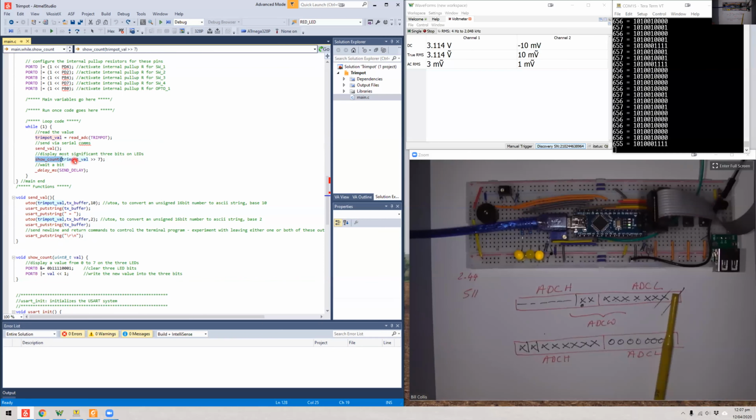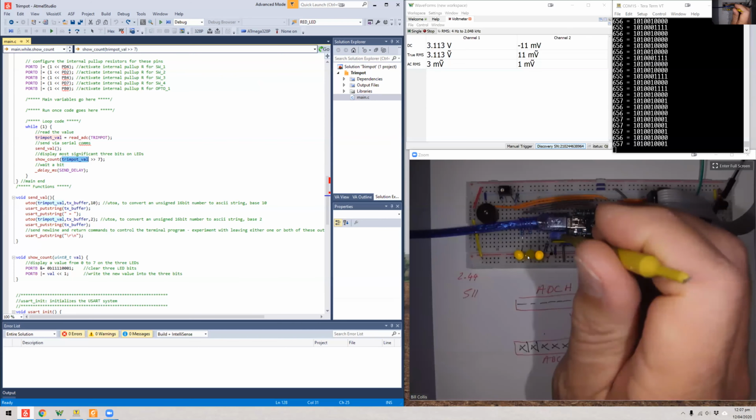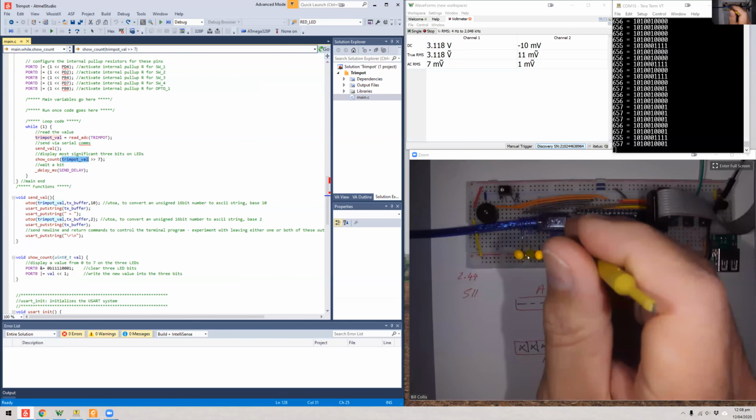And what I'm doing is I'm sending that function the value which is being read, and I've shifted it right by 7. So now I'm back in my 10-bit mode, and I've got this number here, and I'm shifting it 7 bits to the end and passing that to my function, which of course then clears those 3 bits, shifts the value to the right by 1, and then writes them into those bits. So that's how I'm getting a 3-bit resolution, and you can see that my system now requires a significant change in voltage, and the voltage resolution for this is quite different.